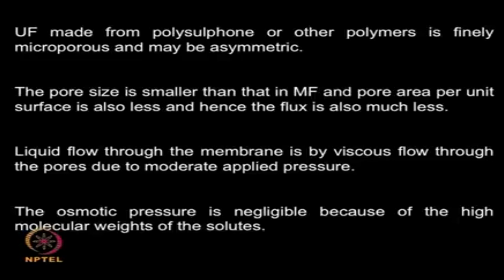The liquid flows through the membrane because of viscous flow, and you are applying moderate pressure here. The osmotic pressure is negligible in microfiltration when compared to RO or nanofiltration, because you have high molecular weight of the solutes. Okay. So microfiltration operates more like a viscous flow.